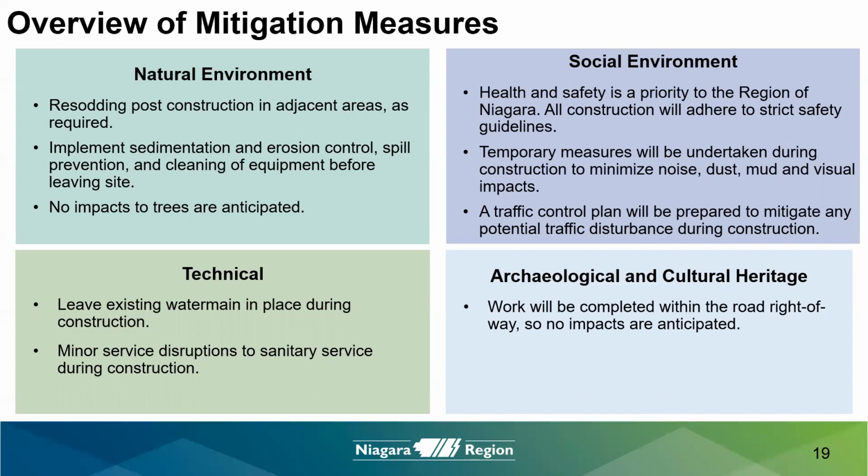No impacts to trees are anticipated with this undertaking. On the technical side, to minimize impacts to local servicing, the plan is to leave the existing water main in place during construction. Minor service interruptions to sanitary services may be experienced during construction while service lines are being reconnected to the new sewer.